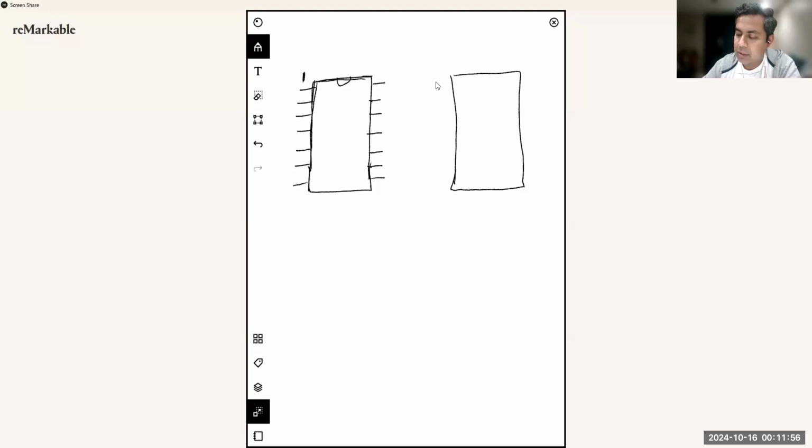So this is pin number 1, then 2, 3, 4, 5, 6, 7, then 8, 9, 10, 11, 12, 13, 14. So that's our NMOS. The code for that is ALD1106. And it's similar to the PMOS, which has the code ALD1107. And it also has 7 pins on each side.